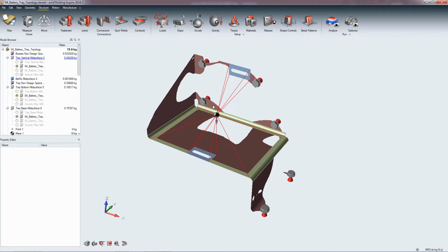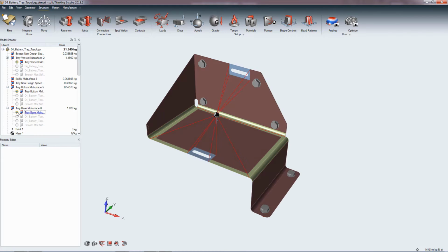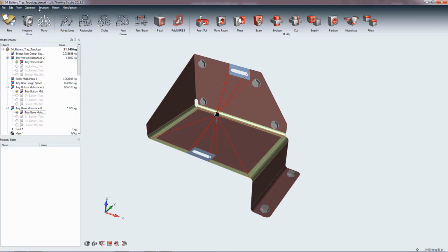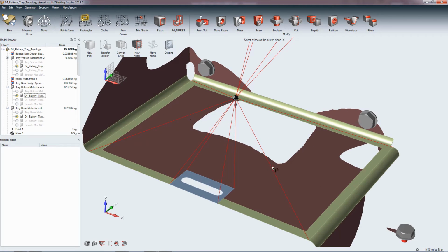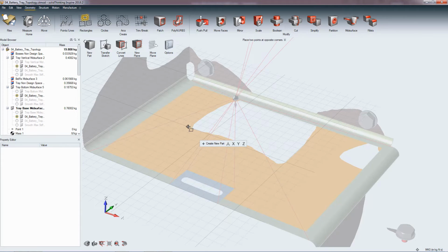From here, I could either export this geometry to a CAD tool, and you can do the detailed design in the CAD, or I can do some simple geometry modifying using Inspire. Let's switch back to this full space, and I'm going to show you how easily it can create some simple geometries. For example, we want to represent this cutout here. I'm clicking this space to draw a box.